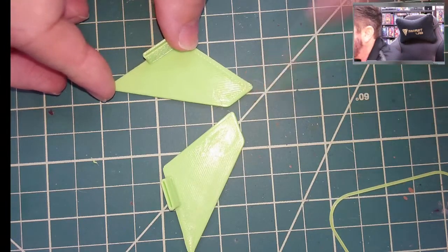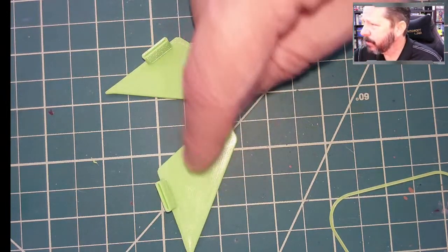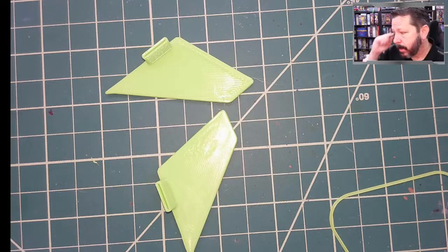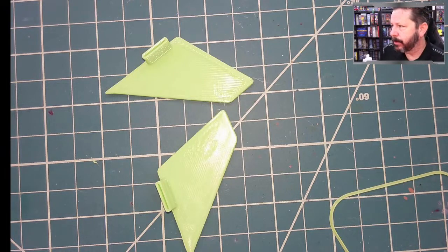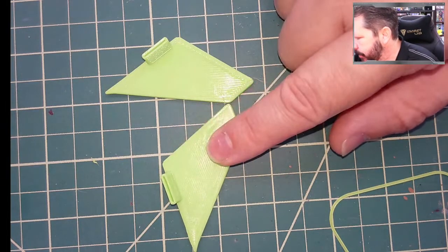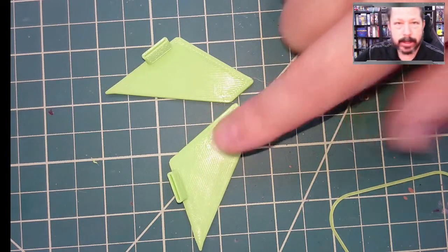But ironing, what it does is it will basically drag the nozzle across any flat surfaces at the top of the model, and extrude a tiny bit of filament to try and flatten it all out. And so there are settings that you can tune to make it a better surface. But if you want a smoother, flat surface, it does have to be flat. It doesn't do non-planar ironing.